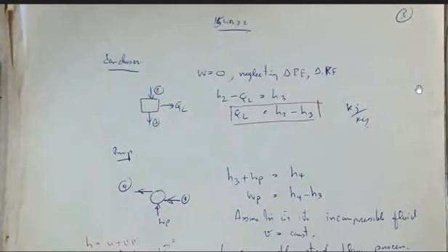Now we look at the condenser. The steam coming into the condenser would be at state 2, and when the steam comes into the condenser, we will have QL out. QL would be heat that is dissipated to the environment to turn the steam at state 2 into water, or liquid form, at state 3.